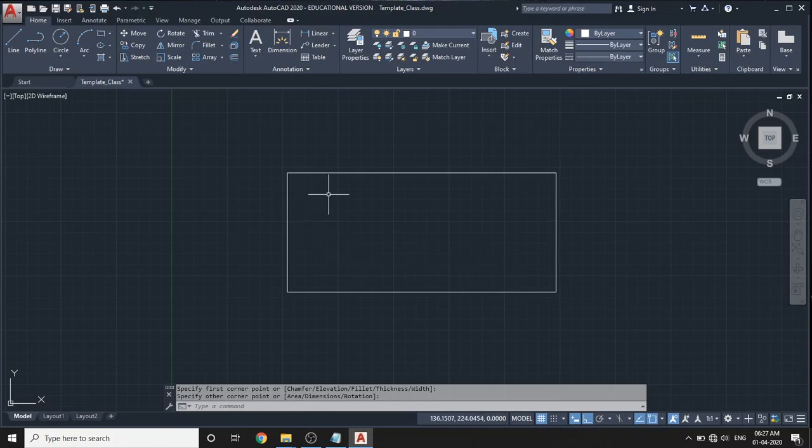Also, if you see the scaling effect, or where the object has to be placed after scaling, we can understand that we need one more input, that is the base point. Suppose I want to reduce the size of this rectangle by 50%, that is to make it half.